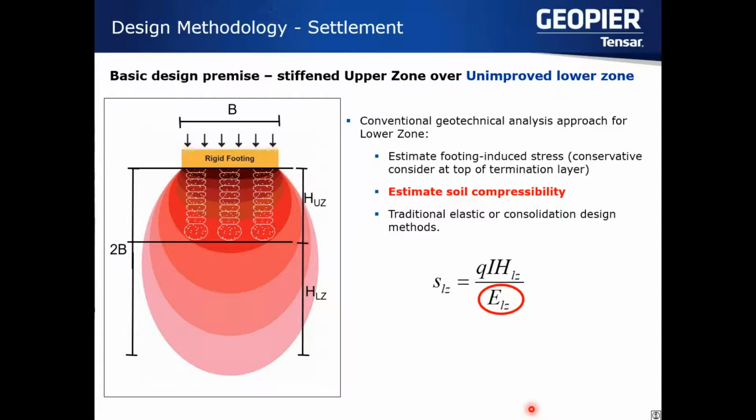So when we're looking at the lower zone, this honestly is where good geotechnical data from a site investigation comes into play. And if we're dealing with fine-grained soils or clay soils, making sure we get some good compression tests at depth, not necessarily 5 feet from the surface, which give us good recompression and virgin compression curves as well. And we rely heavily on that information to calculate settlement estimates.